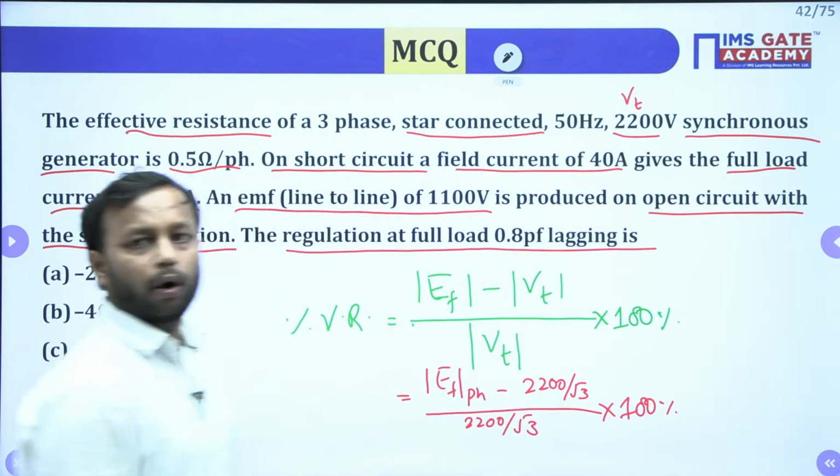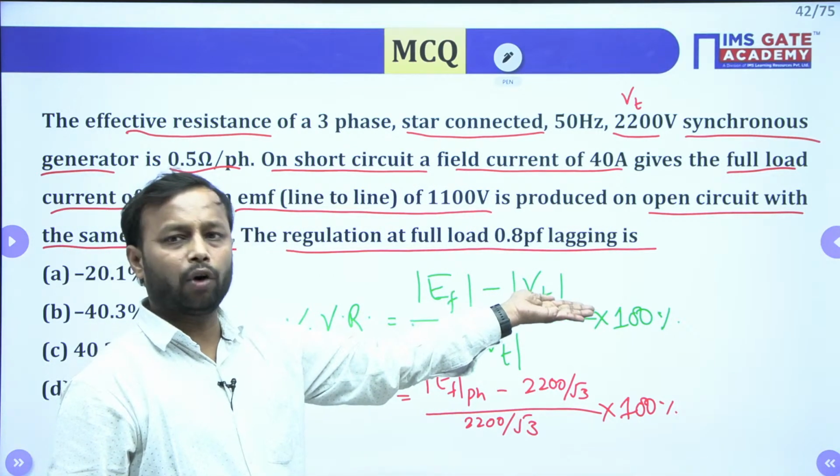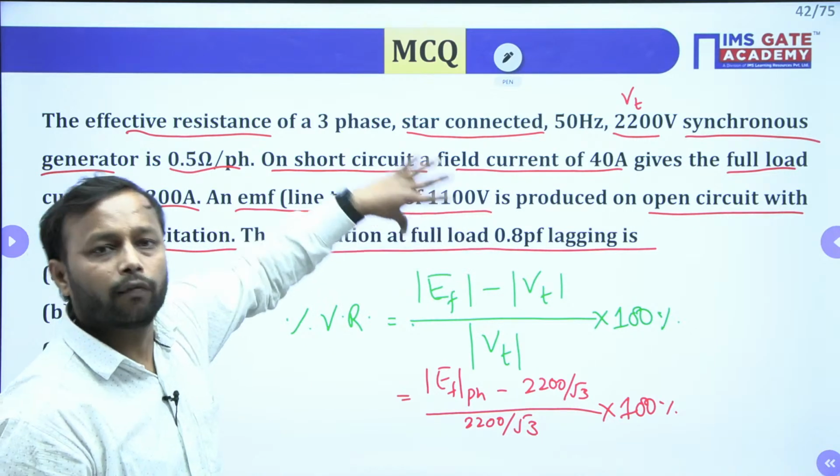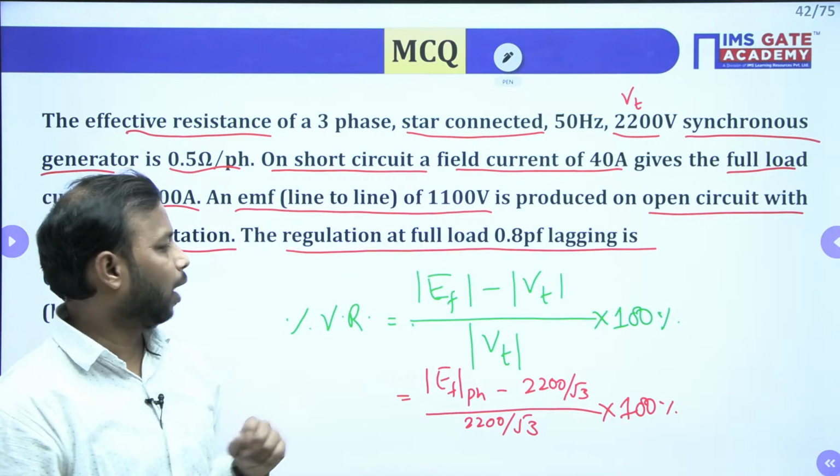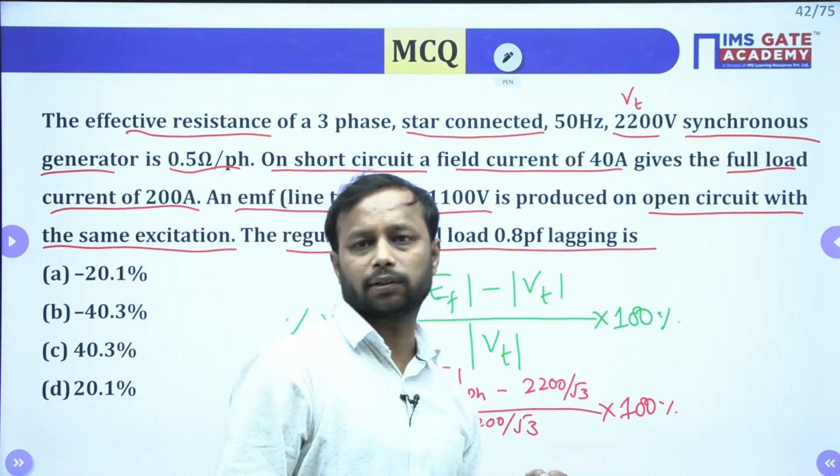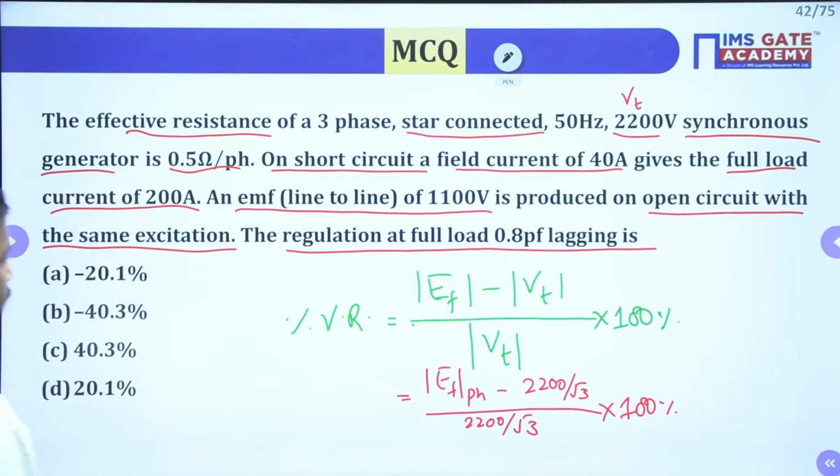If you are taking a line voltage, then your EMF will also have to be in line voltage. Otherwise, you are going to get the wrong answer. Done.